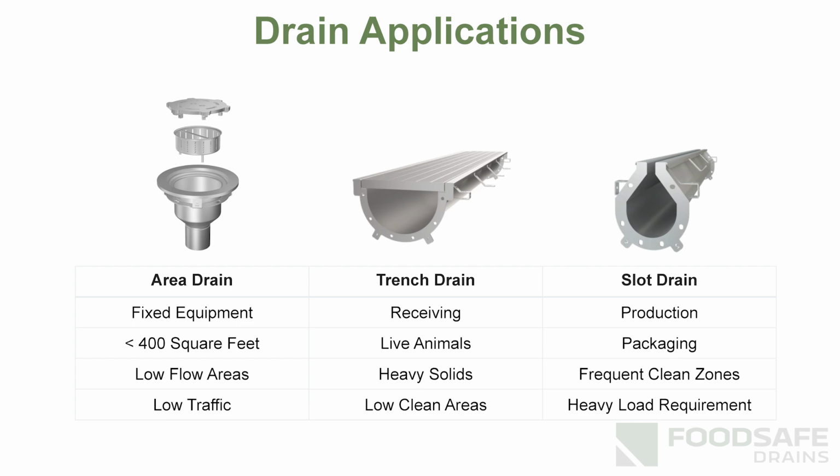Many companies decided, we don't want trenches anywhere anymore, so let's just do area drains everywhere, and that's created a whole other bunch of issues, because now you've got a much larger underground infrastructure, because when you go from linear, you go from a few floor slopes to an area drain approach where you go to multiple floor slopes, and now you've got way more P-traps, way more underground systems, so much that gets added to it.